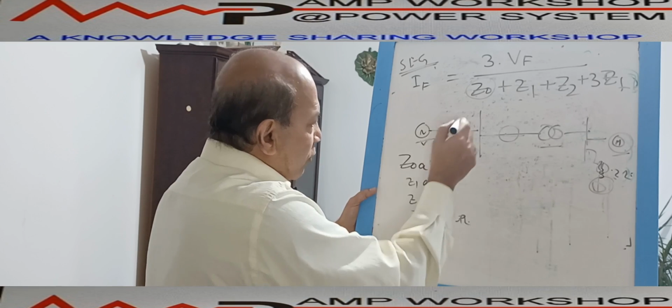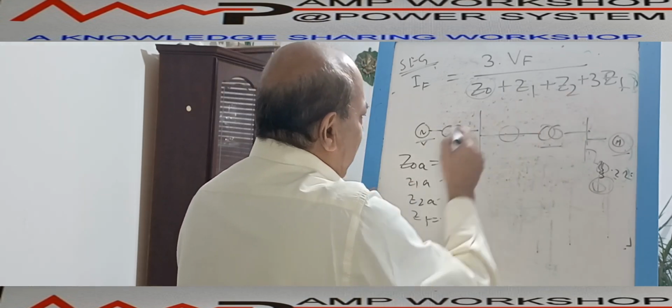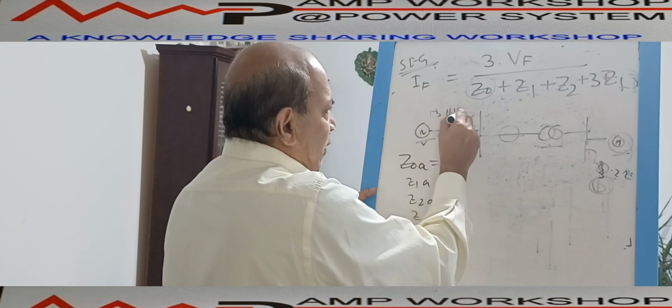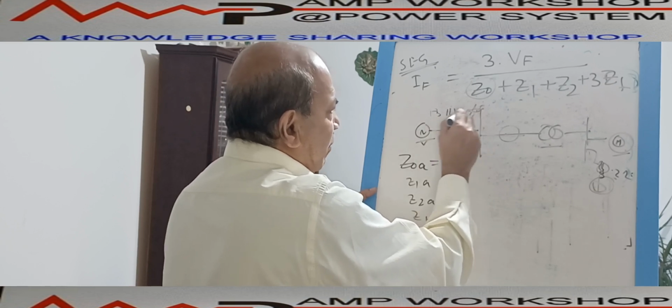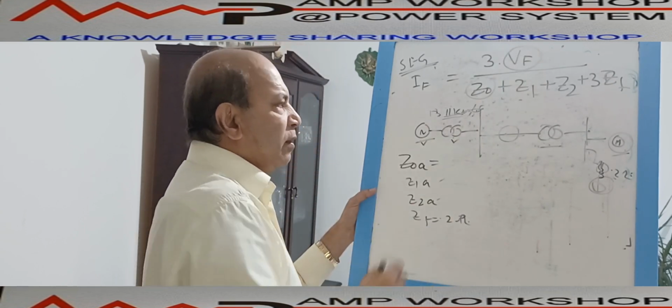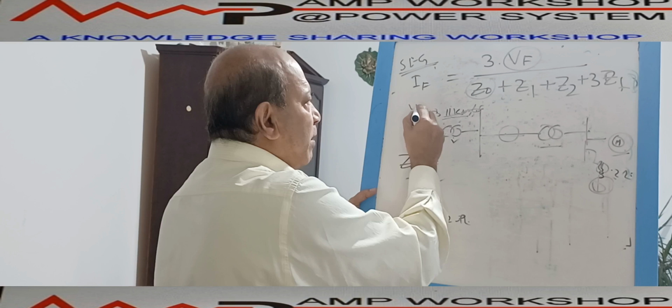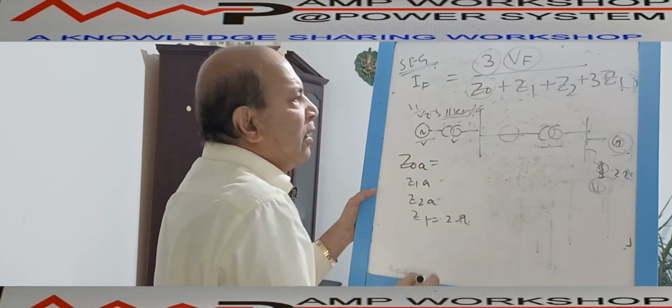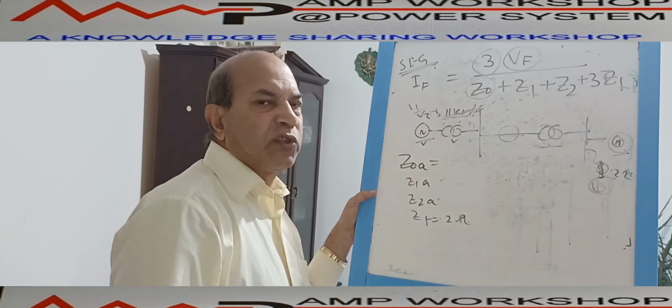Now we can put these figures over here, and we know the phase voltage. Suppose it is an 11 kV system. So 11 by root 3 is the phase voltage, the phase-to-ground voltage VF. If it is 11 kV line to line, 11 kV by root 3 will be the phase voltage. You multiply it by 3 to give you the current for this system.